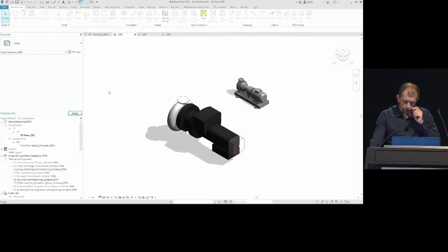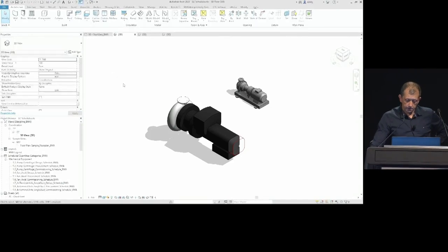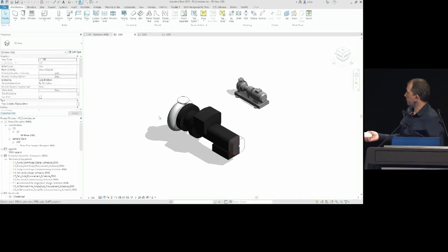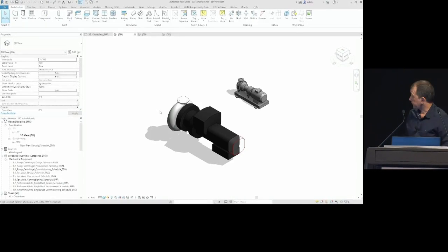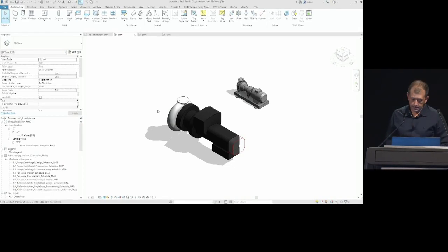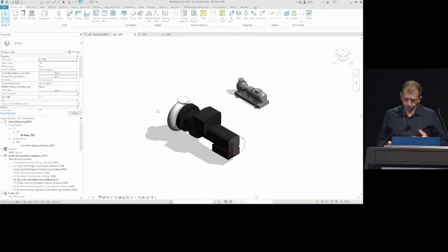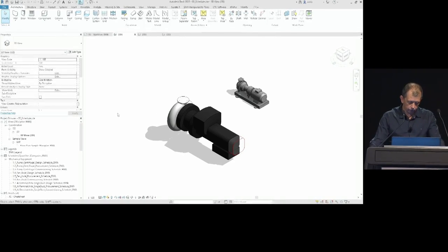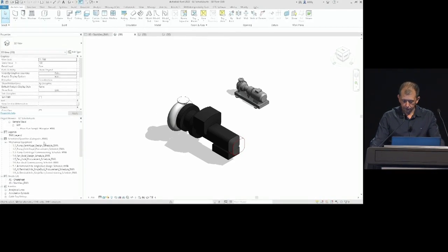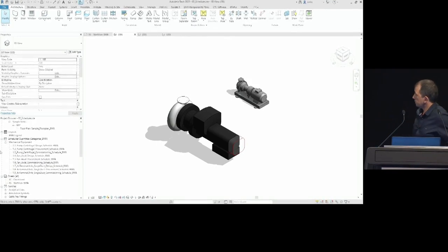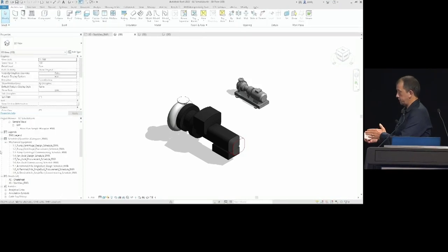The last thing I want to show you here about the template is the schedules. I already mentioned that we have updated the schedule to the shared parameter file version 7. Another thing you should be aware of when you use that BIM-Boss template is that we filter the schedule according to generic families or manufacturer families.